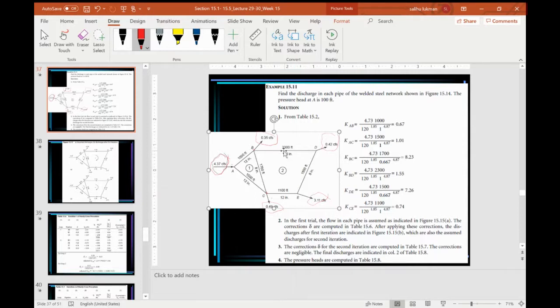Don't forget D. DE, here we add the fire flow, okay, and we divide the flow into from CE to be 0.46, and from DE to be 0.42, and then the fire flow to be 2.23, so that at the end the total flow is 4.35, okay.